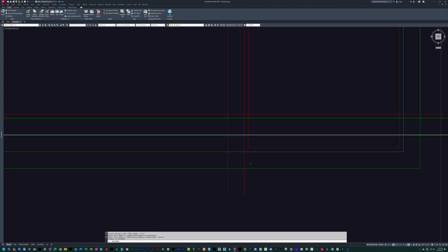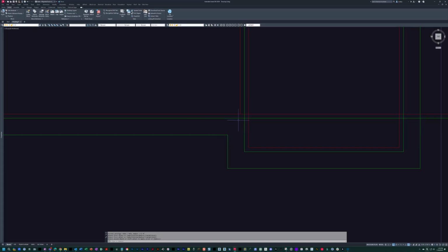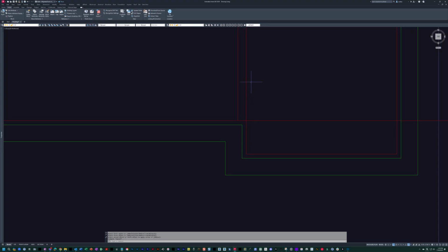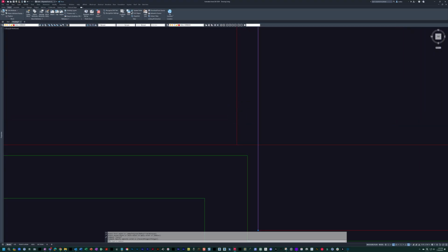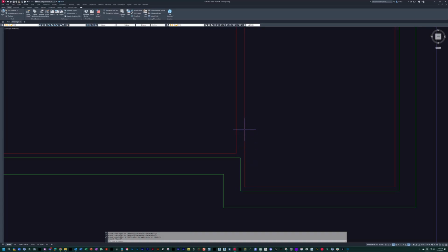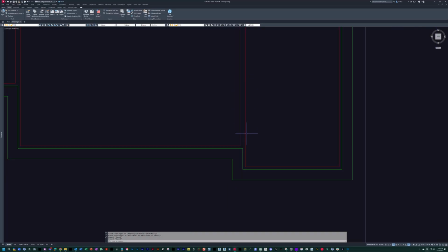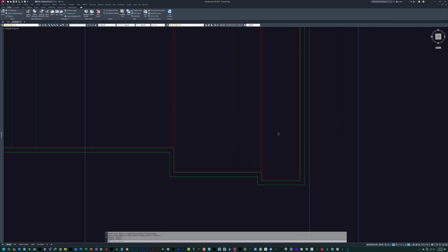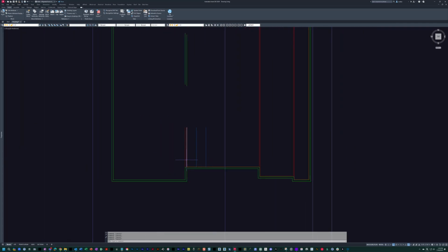And then we're going to match properties and create the exterior bump, and then close out on the inside. So you see we had this line here, and we did a 2 and then 8, and then additionally a 4. And what this allows is my furring to occur here, and then we can line the inside of the wall up right there with the furring and give a really nice clean corner. So there we go. We're making some pretty quick progress.